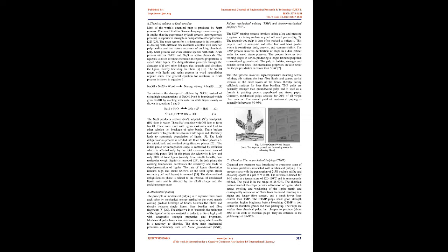4. Ultrastructure of wood cell, pulp, and paper. The raw material, wood or non-wood, consists of cells, and these cells are bonded together by the middle lamella, which is rich in lignin. In the domain of wood and pulp, cells are called fibers and each cell consists of a cell wall and lumen, Fig. 5. Lumen diameter is around 10 to 20 µm and cell wall thickness varies between 2 to 10 µm. 18.